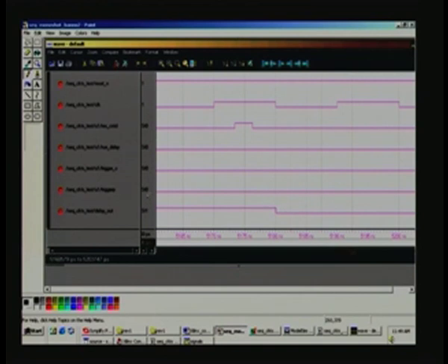We started with 77 nanosecond, you remember. So, the difference is 5180 minus 77. If you take 77 as 80, 5100, and 3 extra we had taken. So, it has given a time delay of 5103 nanosecond. Now, as per our program, it was a setting of 255, and we also saw that the clock is 20 nanosecond. So, 255 into 20 is 5100.